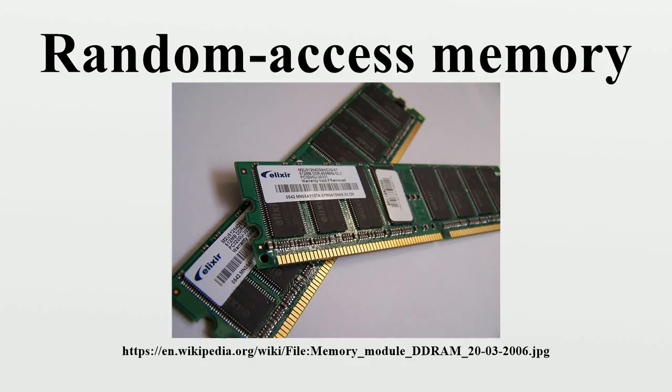ECC memory includes special circuitry to detect or correct random faults in the stored data, using parity bits or error correction code. In general, the term RAM refers solely to solid-state memory devices, and more specifically the main memory in most computers. In optical storage, the term DVD-RAM is somewhat of a misnomer since, unlike CD-RW or DVD-RW, it does not need to be erased before reuse. Nevertheless, a DVD-RAM behaves much like a hard disk drive, if somewhat slower.